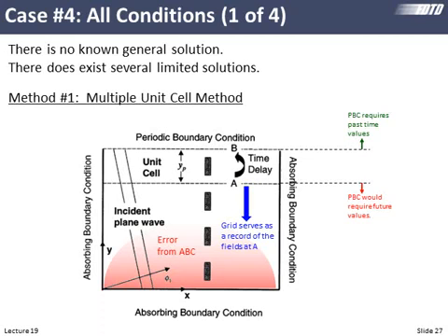And essentially, we're interested in this model here. So we have one unit cell in memory. But what we'll do is we will actually be modeling a bunch of other unit cells this way. So we can have a plane wave traveling at some arbitrary angle. It will look crazy here, so it certainly won't be correct here because we can't do periodic boundary conditions. But as you move away from the boundary or this error region that I'm showing in red, it really does start to look like a nice plane wave at this boundary, and we really can have a plane wave at some angle.